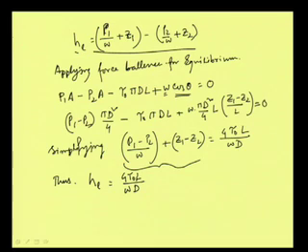Well, from this expression we can rewrite this into a different form. It can be written as 4 tau 0, and we are writing it this way with a definite intention, equal to the head loss HL, which we are writing on this side, into W into D by L. So, 4 tau 0 is equal to W D HL by L.